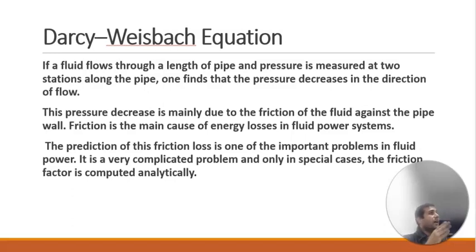If it's not a horizontal pipe, it's a different story. The reduction is due to gravity, due to the head losses, because gravity is pulling it down. Okay. Now, we always presume it's completely flat. They will mention that to you. They will say it's flat, it's horizontal, or it's at a 30-degree or 20-degree angle. They will give you the whole length, how far it is from here and how high it is from here. And based on that, you can calculate the length using the Pythagoras theorem.